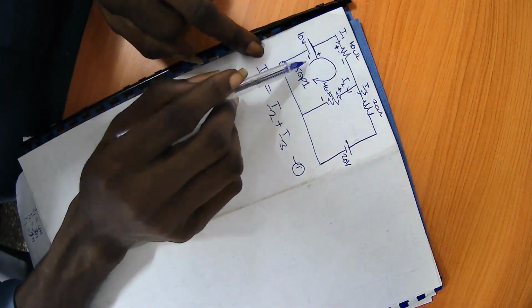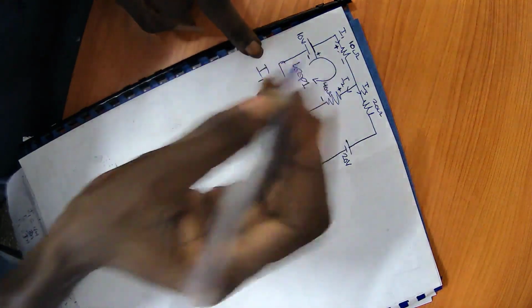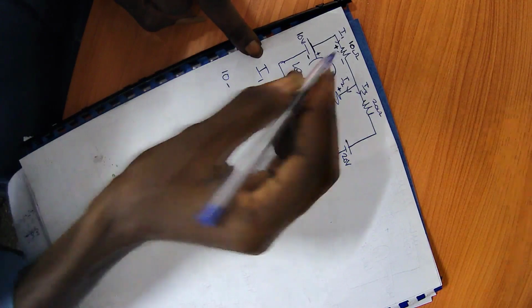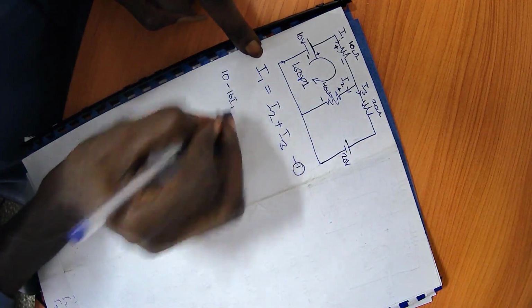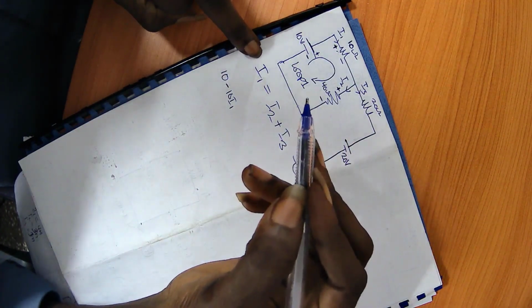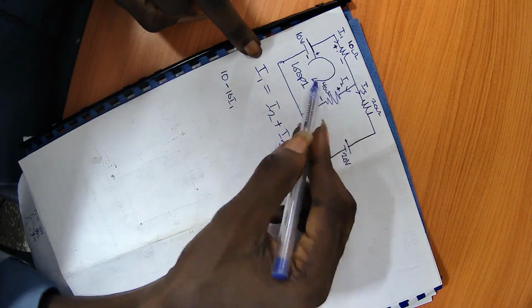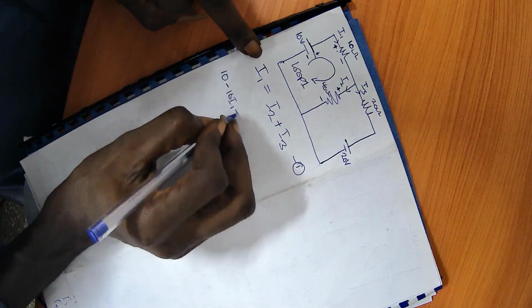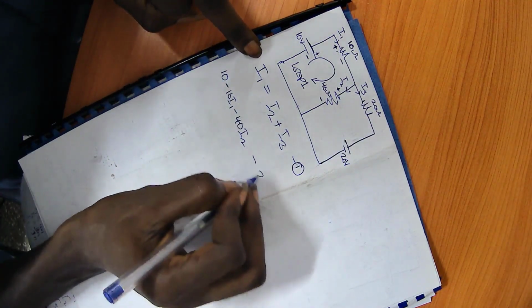But when you come to this voltage, you see that it's from the negative, it's increasing to the positive. So this voltage here will be positive. Okay, so then here will be negative. So minus 10 into I1. Here from positive to negative, that means it's decreasing. Okay, or the loop is in the same direction as the current. That means there's a voltage drop, or voltage is decreasing. So minus 40 I2. This is equation 2.